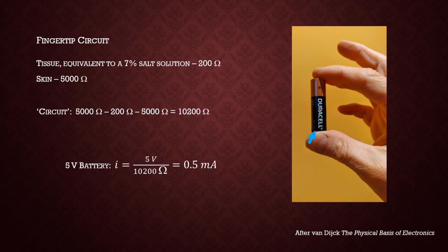Not going to really feel like that. I get to 10 volts, and I'm starting to get to a range where I might start to feel things. Certainly when I get to 100 volts, I have 10 milliamps, and that's approaching damage level. So you can see that depending on the voltage source, you can run into danger.